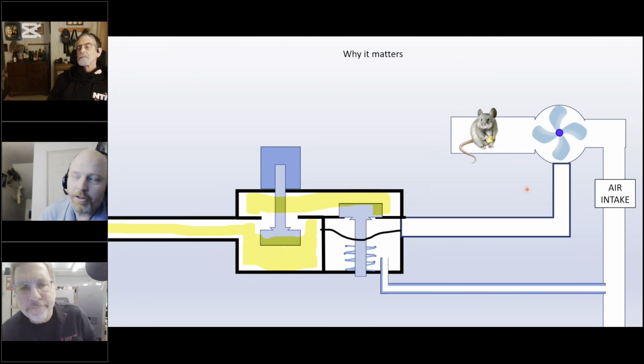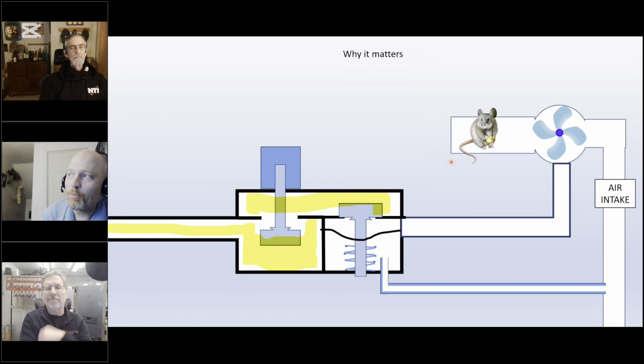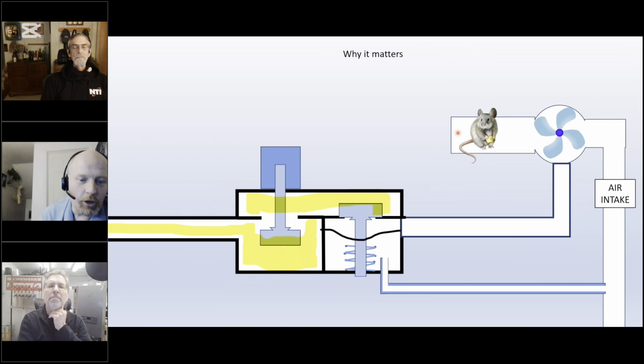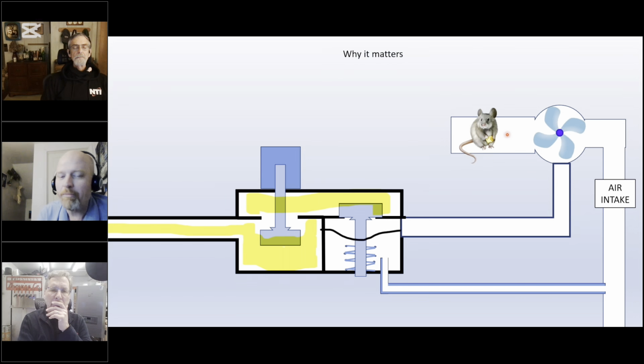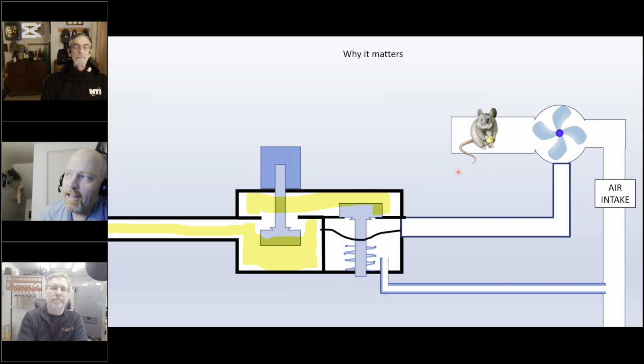So if the venting is clear and clean, what I can pretty much guarantee is you'll get a very low pressure. If it's 2-inch venting, the pressures typically range up to about 1.25 to maybe 1.5 inches on the extreme. So 1.5, I'm going to say, is the maximum you should see on 2-inch venting ever. If you're on 3-inch venting, typically never more than 1/2 inch, and that's suction or positive pressure, depending whether you're checking the intake or exhaust.